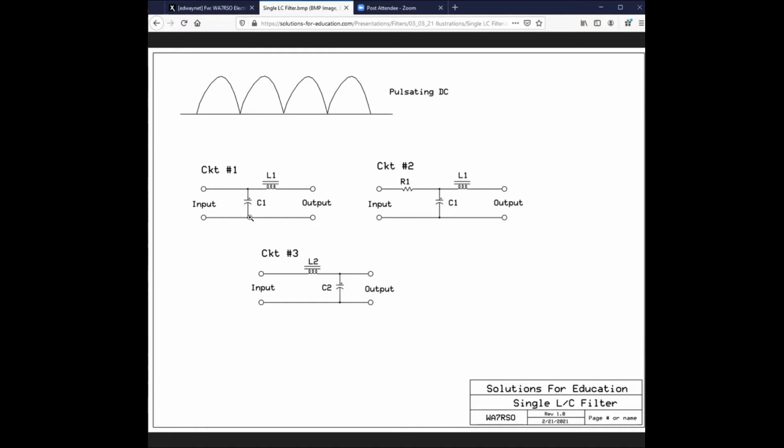So as this guy here is charging, reaches on up like this, by the time it gets up about there, the coil at this time is starting to say, well, maybe a little bit. However, when you start down the other slope, what's going to happen? This charged capacitor does not like changes in voltage. So what does it do? It starts to dump. And when it starts to dump, it's going to go right through this coil. So the current through the coil will increase while the capacitor current decreases.